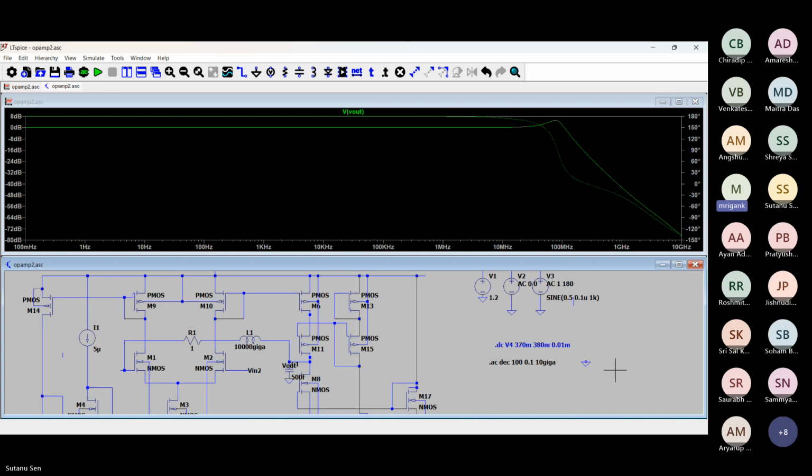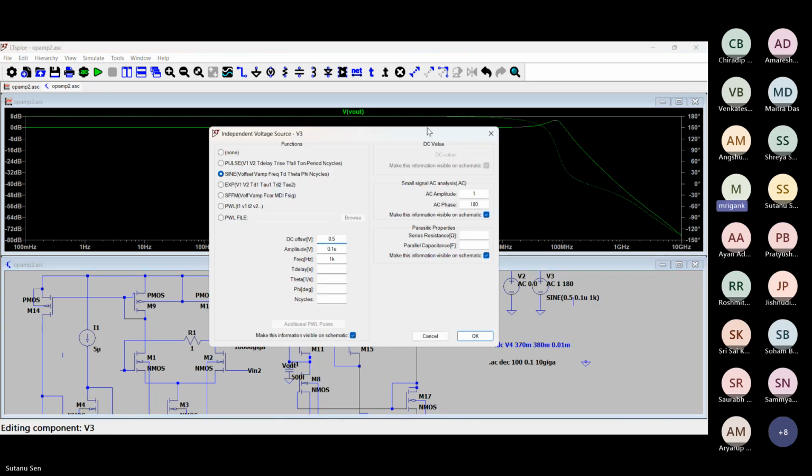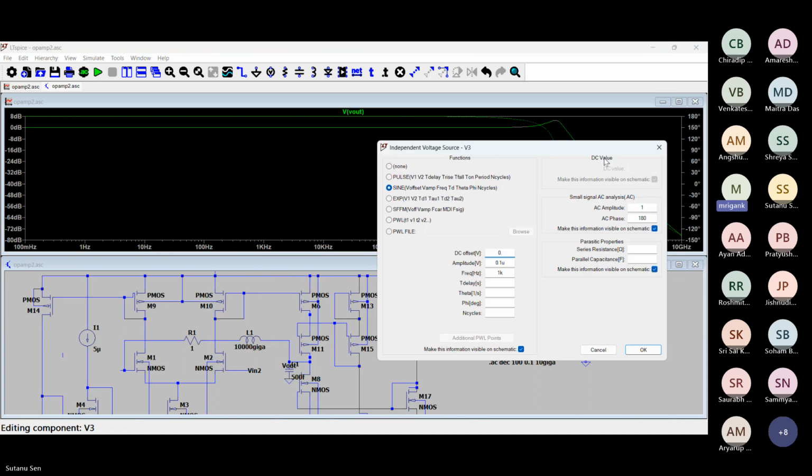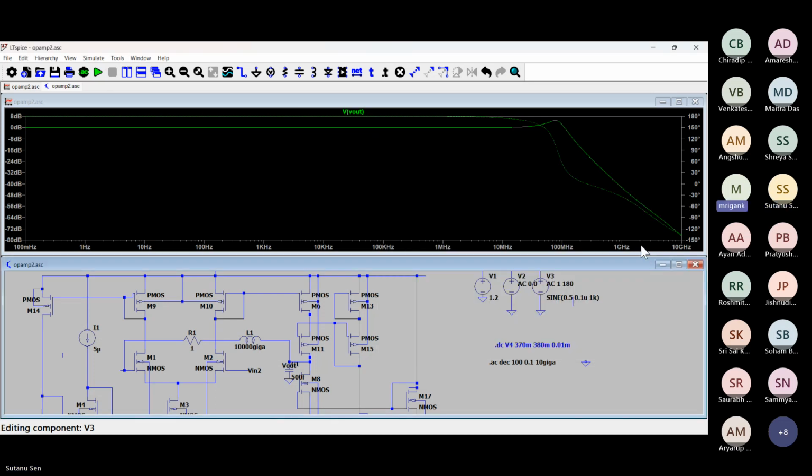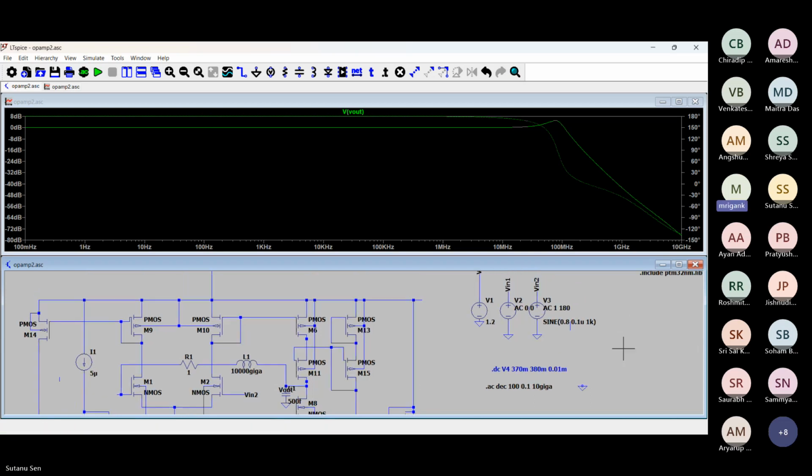And LC, C is here. So can we, the DC gain, AC point of view, shorted, circuited, but still not getting it basically. Output DC, you check, output DC is coming properly. Output DC anyway we saw, so that was coming properly. Yeah. But AC gain is not coming. So although it is an ideal L, and omega L should be very high, even for 100 hertz, omega L is very high, but that's not coming.